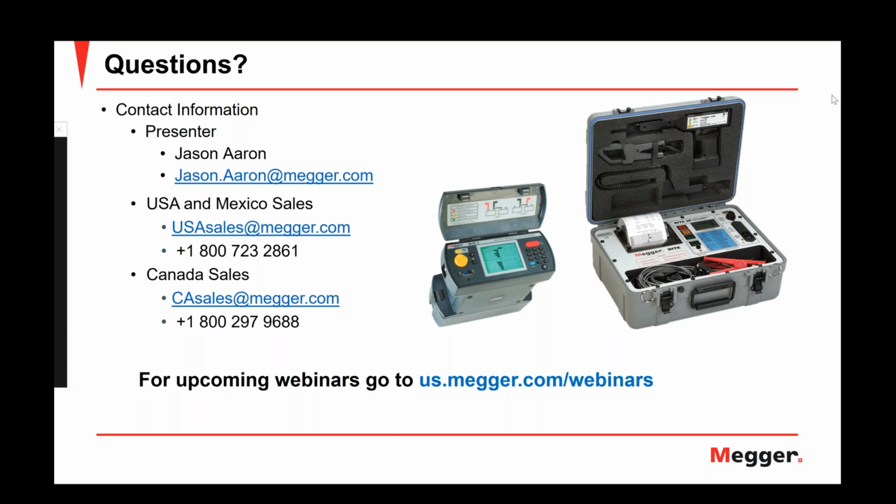If you have a valve regulated lead acid battery, for example, where you have no access to the electrolyte, the best way to get the temperature is going directly to the negative post of the cell or cells that you want to measure. The negative post is where all the chemical reaction happens, and if there's any internal activity in the battery, the temperature will be increased mainly on that terminal post. So that is the best way to go for the temperature.